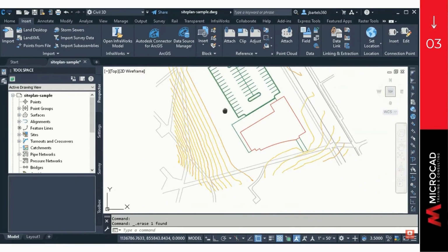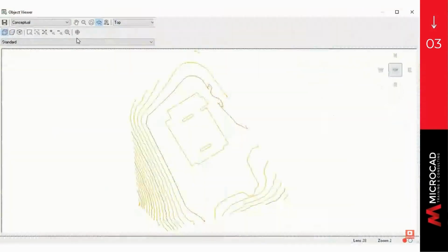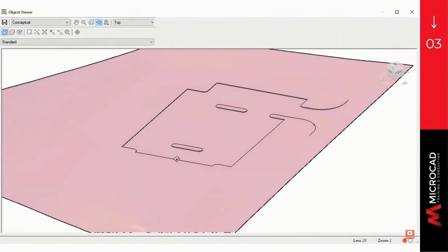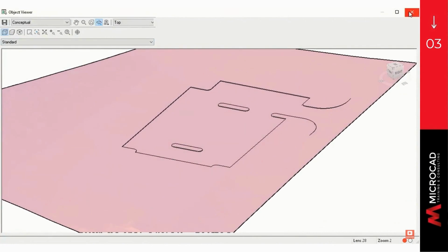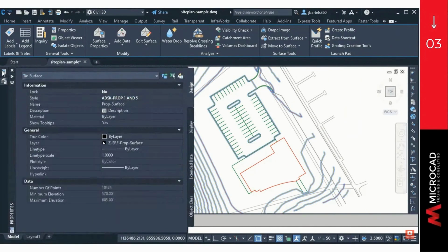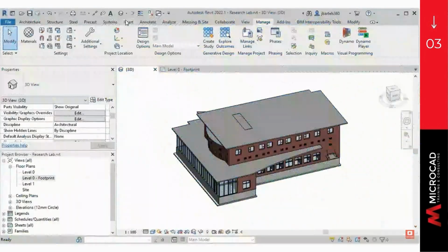So as we can see in the video, we're able to export the relevant data from Revit, modify it within Civil, and once we have made all our changes, we will be able to reintroduce those changes into the Revit environment. As you can see here, we already have our file with our topo lines, topo surfaces, and the topography created.